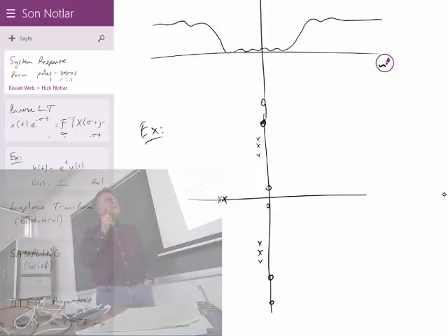This kind of a tool makes the fundamentals of filter design in signal processing. People who know signals and systems, signal processing, well, if you know that, your boss may ask you to design a filter. And the way to design a filter is to locate the poles and the zeros to satisfy your shape. Then, of course, you have to proceed further, because it's not only signals and systems that an engineer must do, you must also implement it.